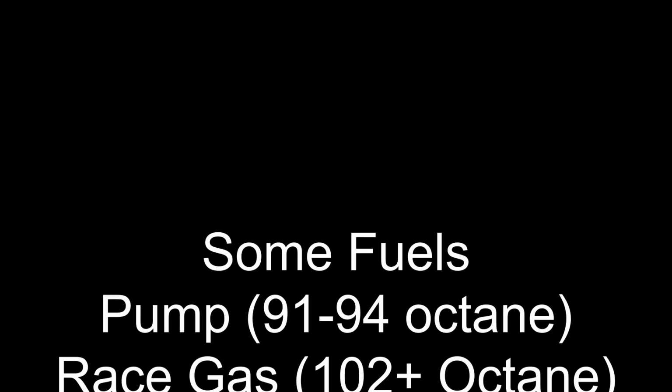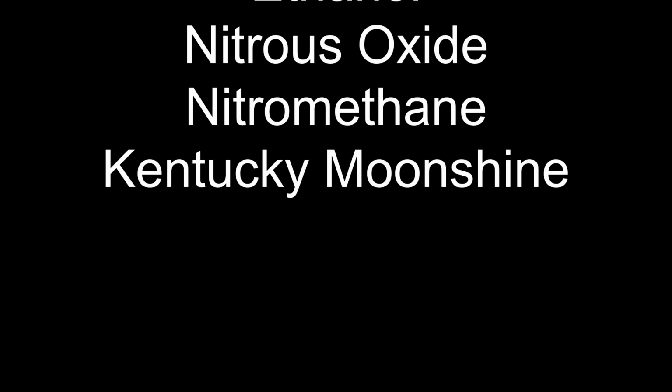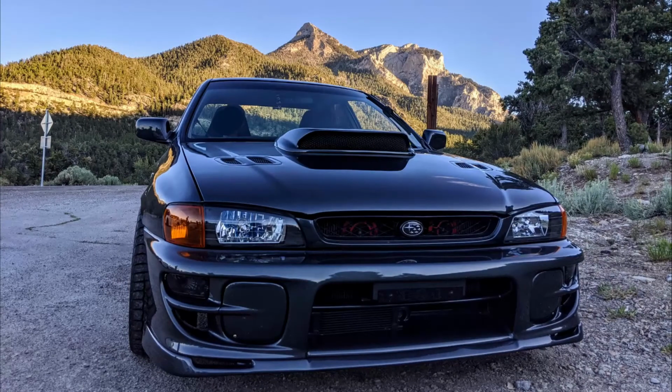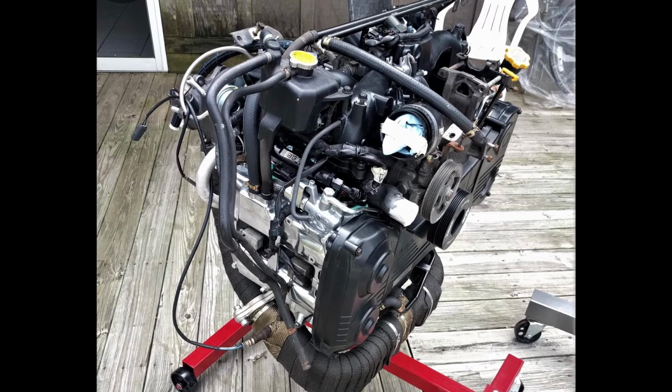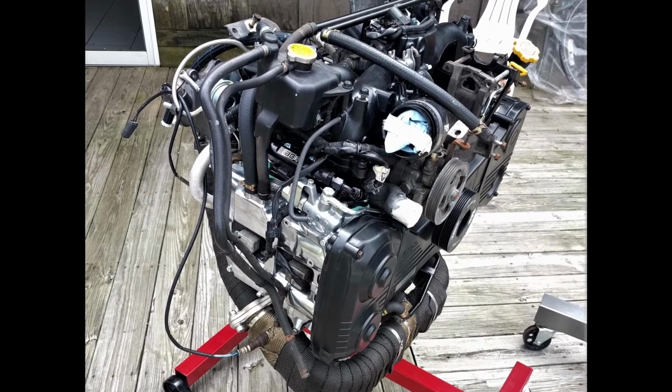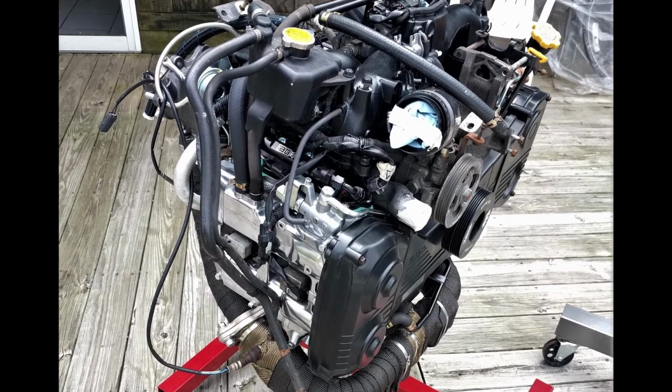Upgrading your fuel system can certainly be considered a power modification. You cannot make power without fuel. Now, the fuel that you select and how it is delivered is how you support your power goals. My goal with Benji was to make 350 wheel horsepower, and I'm pretty sure somebody somewhere has made this power with all stock components. But with all the upgrades I have, this number can easily be achieved, especially if I were to use E85, meth injection, race fuel, or nitrous oxide.